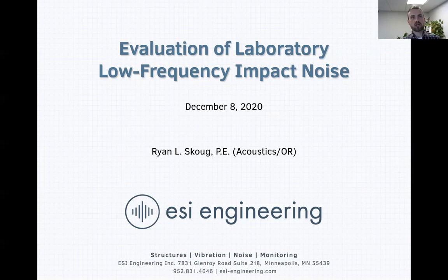Now we're going to continue our evaluation of the ASTM working group rating, the LIR, the low frequency impact rating, looking at how other researchers in this country and abroad have been looking at low frequency impact noise, and also how laboratory tested assemblies are turning out when we compare them to the LIR and some other impact ball rating methods. We've been looking at all of it. We just want to present some findings, show some of the areas where we've been struggling with the LIR method, and also some other options for how we might be able to look at it.